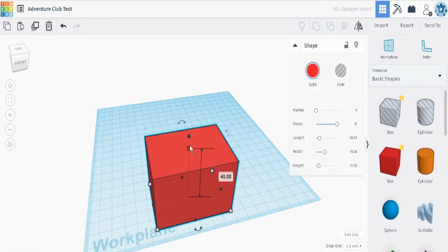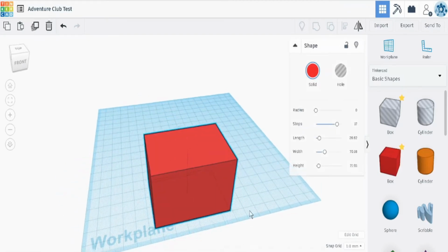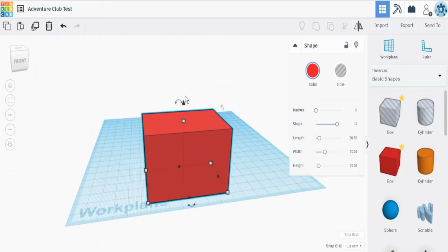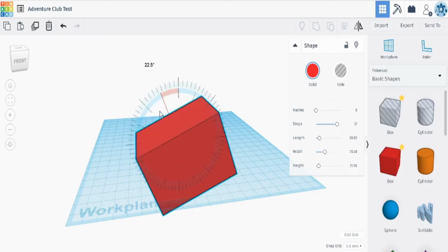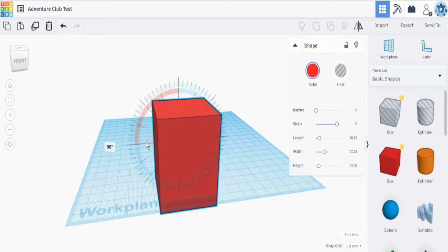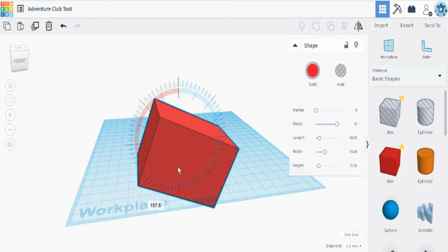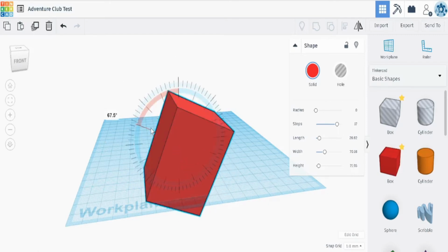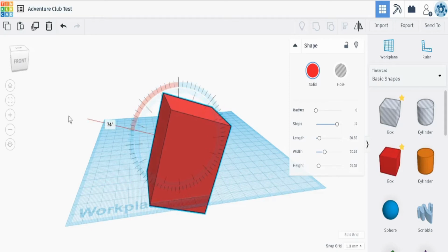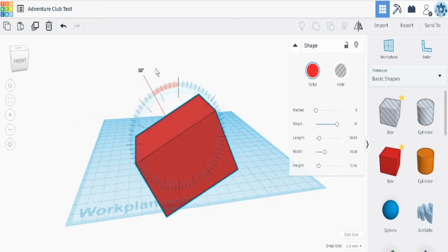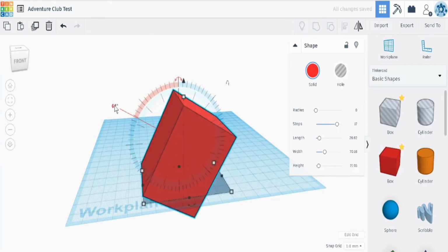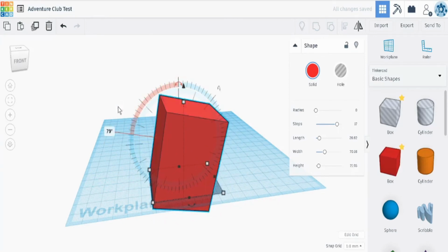And same with if you need it to lower it down from underneath, just look at the bottom and the arrow will appear. Now, the double arrows right here just lets you rotate it. If your mouse cursor is more to the inside of the circle, it will change it by 22.5 degrees. If you want something more precise of an angle, just move on the outside of the circle and it'll let you change it one at a time. And like always, you can always click on it and enter in the exact amount that you want.